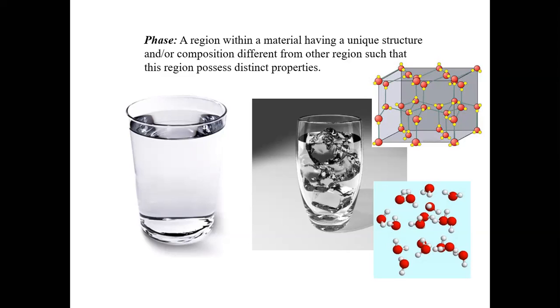Okay, I know this is a little counterintuitive, but that is what's happening. Now if we keep this in mind, it doesn't really matter what temperature you have or what macroscopic phase you observe. In liquid water at a temperature higher than the freezing point, you are always going to see, although very temporarily, these ice nuclei. Now, what's going to happen to these ice nuclei when you cool the system below the freezing point?